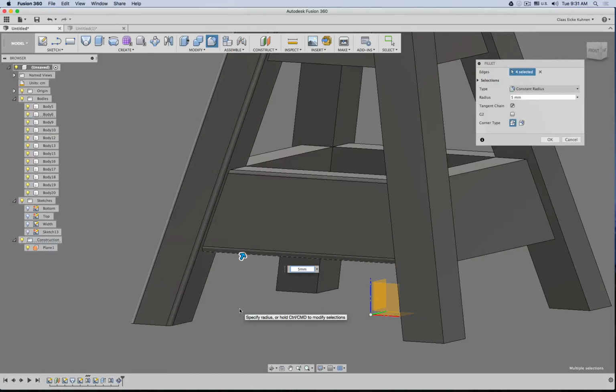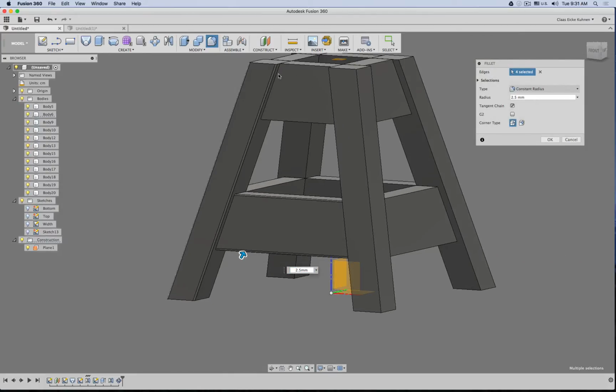But in those areas here, we can actually round or break those corners, because first we can hurt ourselves. Second, sharp corners with shoes, the sole can rip off the corners and damage it. So when we round it, we protect it a little bit, and visually it looks better. And these inner corners here, we don't really need to be concerned about. So there, we can just add all these corners, for example, to it.